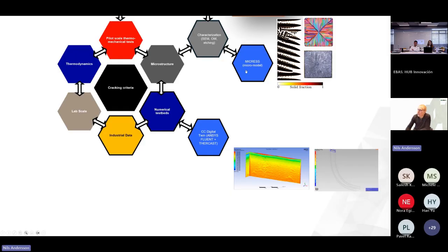So now we have a gap here. How do we bridge this gap? And I think that was part of what Michele asked about as well. So we have one model for the mold, and we have another model for the secondary cooling, where we can have a traveling slice going through the whole secondary cooling region and describe the entire solidification length.